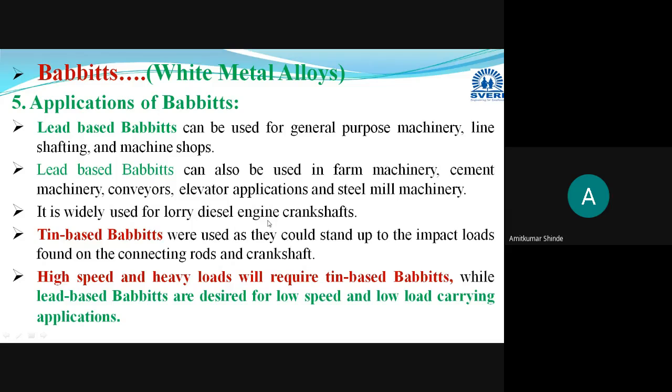Then in lorry diesel engine crankshafts, or connecting rods, for this application we are using the tin based babbits. Tin based babbits are the bearings used in lorry diesel engine crankshafts. Another application I have included is in connecting rods and crankshafts, where high impact load is there.